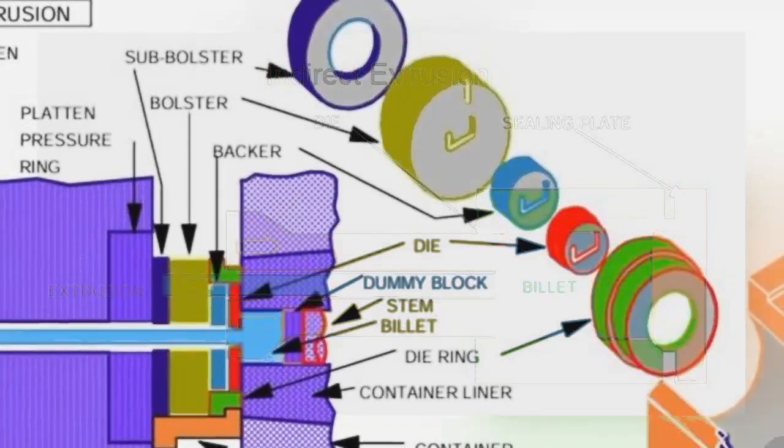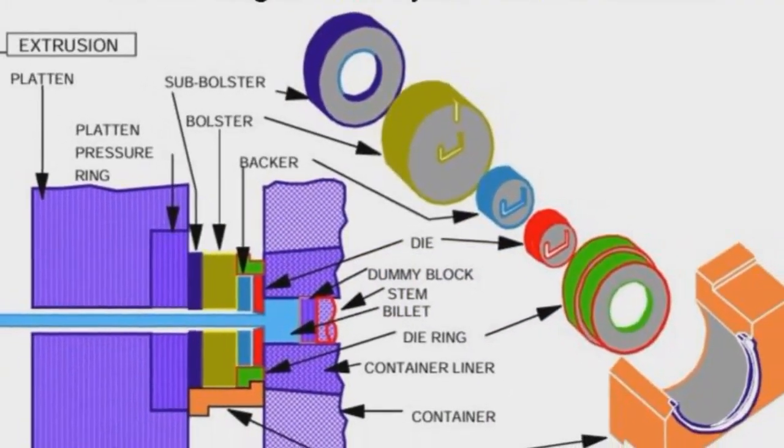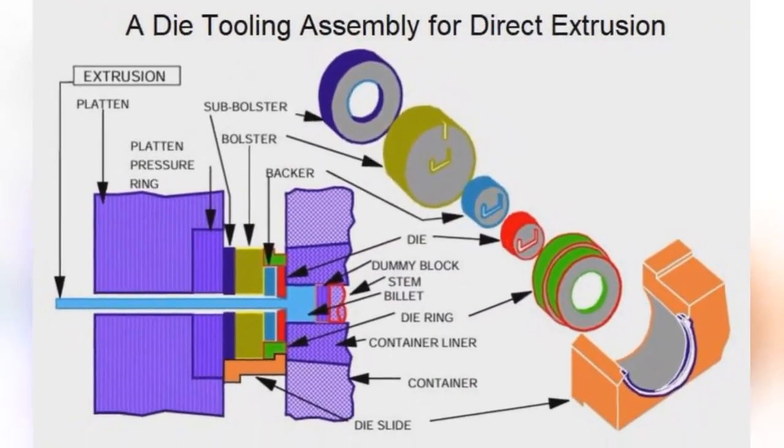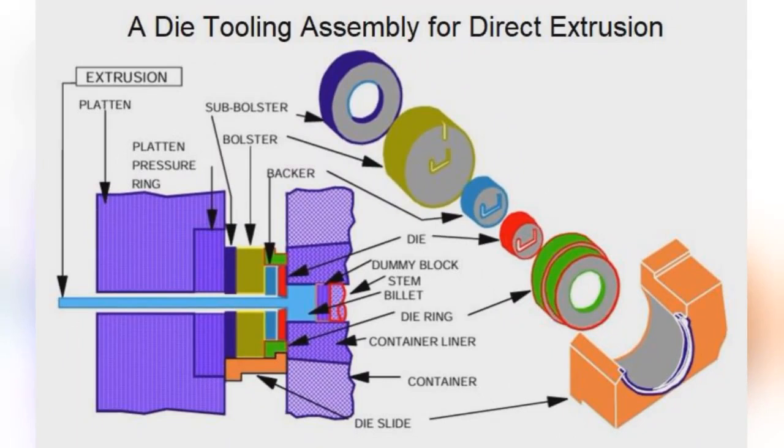In the direct extrusion process, a heated billet is placed in a heated container at temperatures around 450 C to 500 C. These temperatures significantly reduce the flow stress of aluminium alloys, facilitating shaping. Once the ram applies pressure to the billet, the metal flows through the die, shaped according to its design. The die defines the cross-section of the final product, influencing its properties and applications.